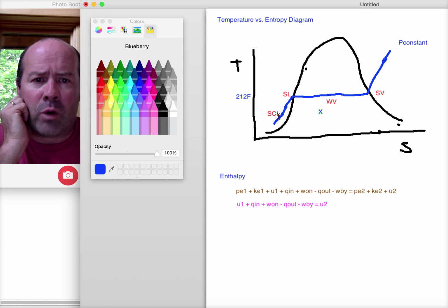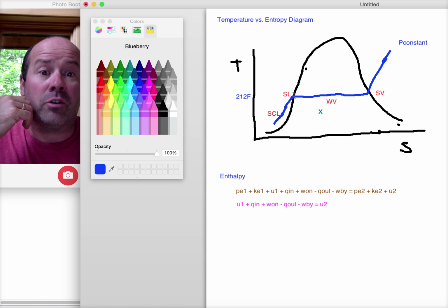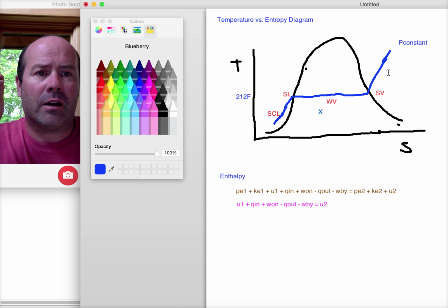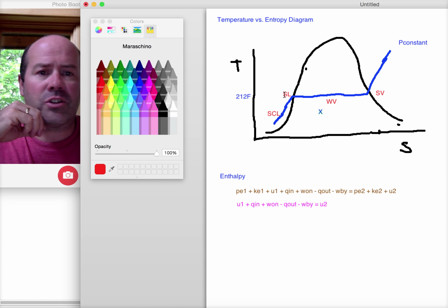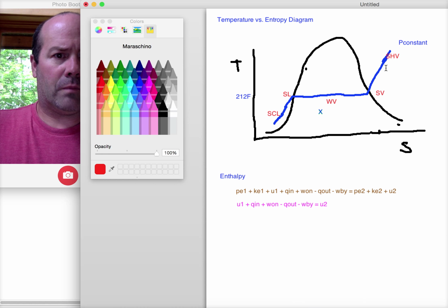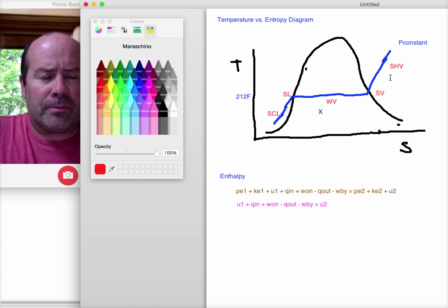So imagine you've got your water on your stove, you heat it up, it goes from liquid to beginning to boil, partially boiling, 100% boiled. Now if you keep putting energy in, the energy is going to go to taking the steam to a higher temperature, and up here we have what's called the superheated vapor. And that's a region up there. So those are the different phases.